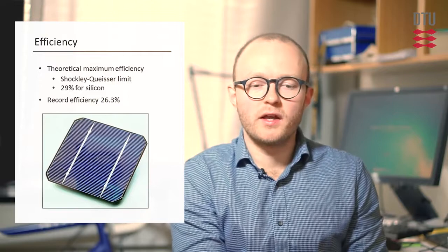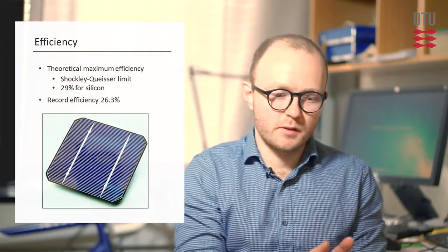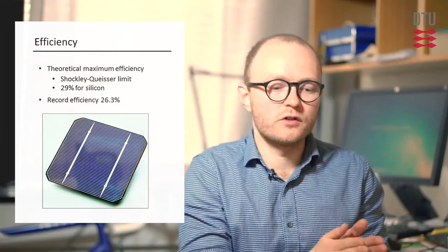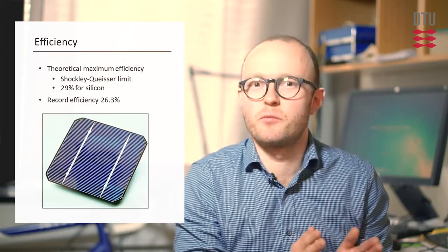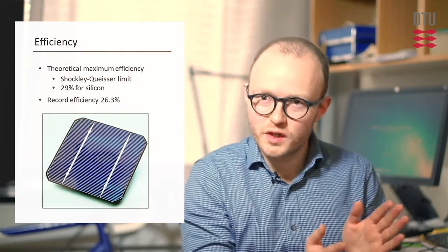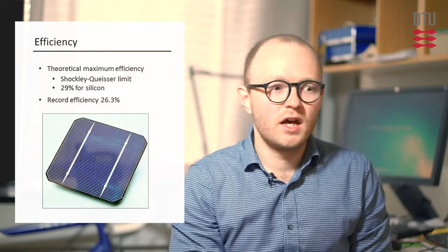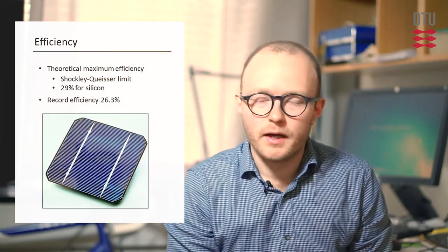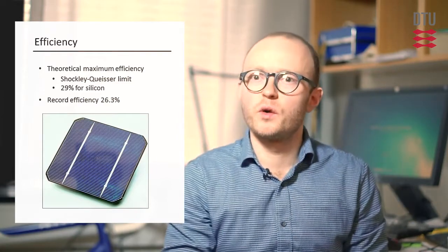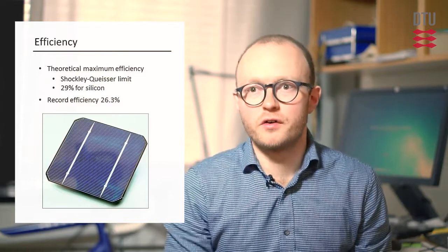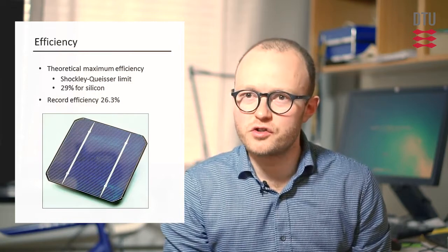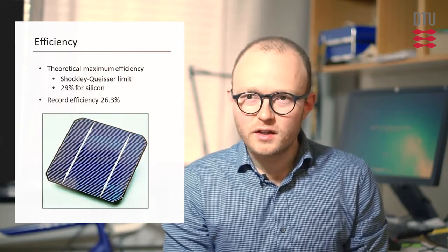When we now talk about making cells thinner, as I said before, there's actually potential gain in the efficiency to be reached here. There's also a reduction in price, of course. The smaller amount of silicon we can get away with using and still create the high efficiency, the cheaper the production, at least when it comes to raw material usage. But there are some practical limitations: when we get below, say, 100 micrometer thickness, silicon wafers become very hard to handle in industrial production.